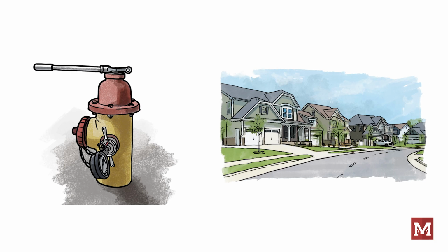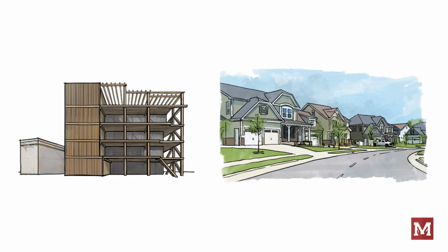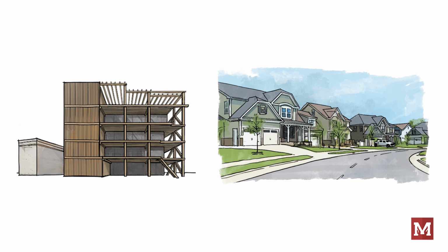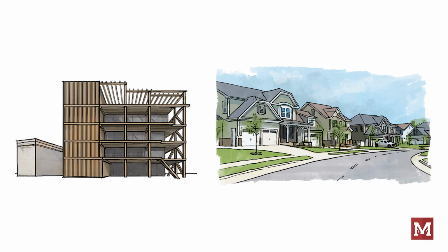Clearly, that's not an adequate picture of the water supply. Designing a system with that level of information would be like building a condo building on the shoreline above sifting sands. It's not an adequate foundation. So we've explained to our client that if we attempt to design a system without having all of what we need, everything we design from pipe diameters down to the sprinklers we use, think K-factor, coverage listing, spacing, etc., is just a wild guess at best. When it comes to fire protection, guessing should not be part of our toolbox.